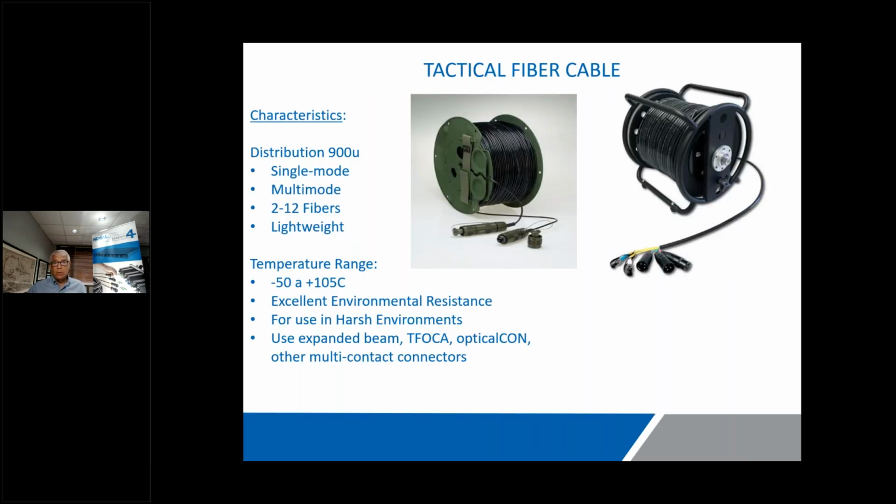One of the subcategories of fiber cable is called tactical fiber. What does tactical mean? Well, it means in reality different things to different people. It means either it complies with a specific mil spec or that it complies with a manufacturer spec under the generic description of tactical.